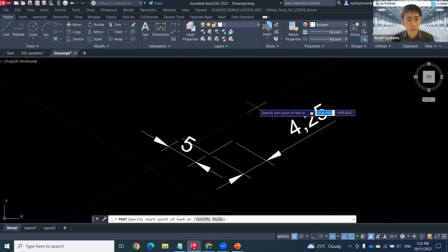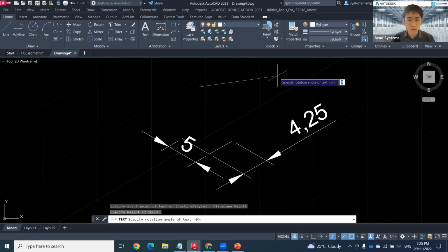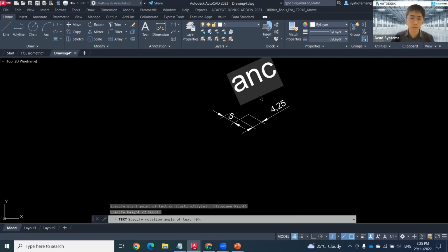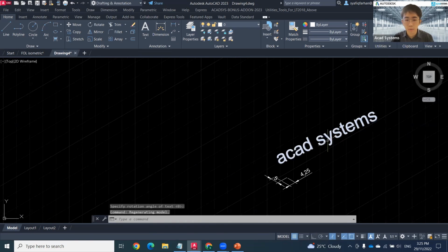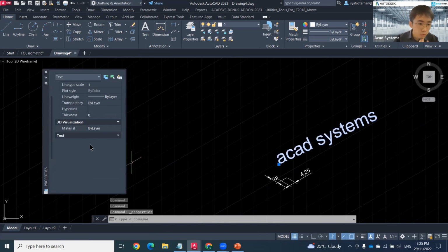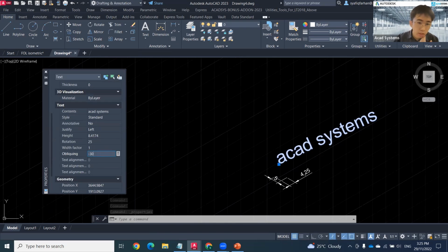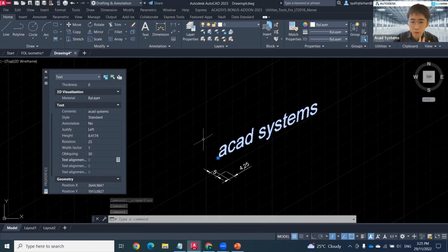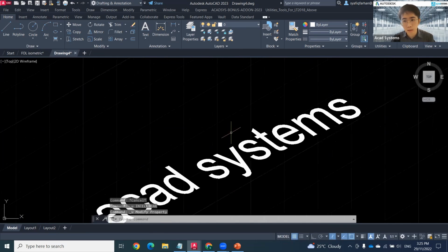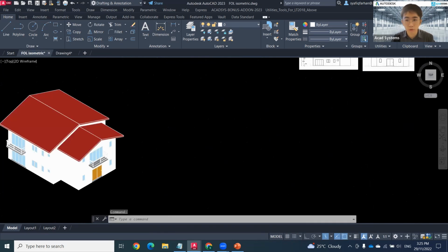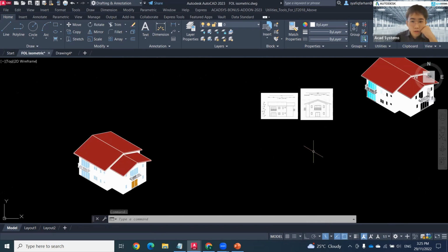And there's another thing called single line text. Okay, so I draw something like this, and I simply type something like CAD system. And this text is not horizontal, but I want it perpendicular to the isoplane we choose. So we can click on it, right click, properties, and we go to find this obliquing. Let us try -30. Okay, so we made it 30. Yeah, so it will be parallel to the isoplane we choose. Because just now, this is not what we want in our drawing when we want to place some text in our isometric drafting. So that's all for the isometric drafting class today.